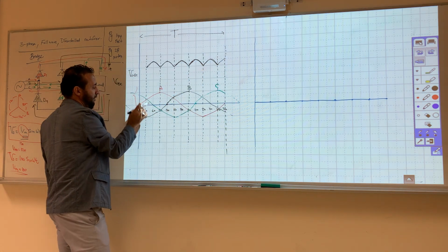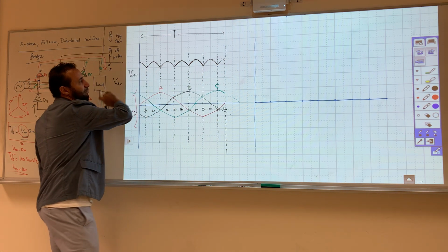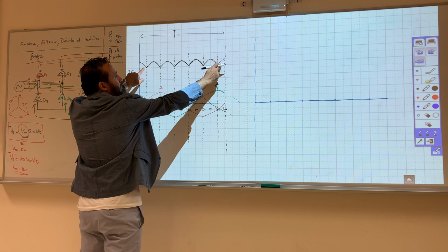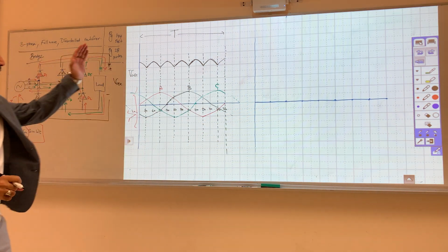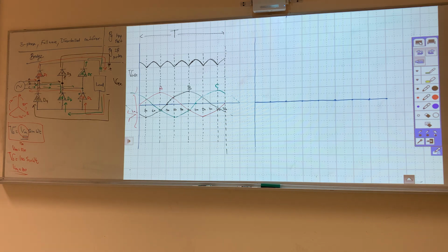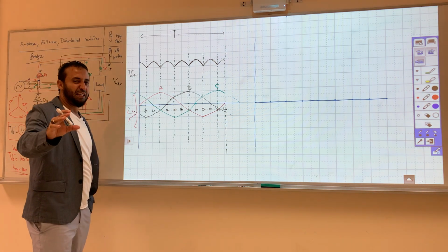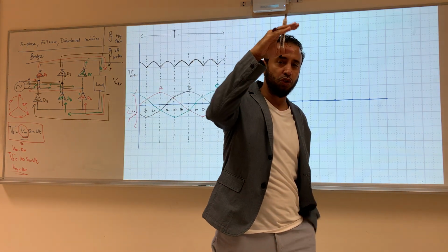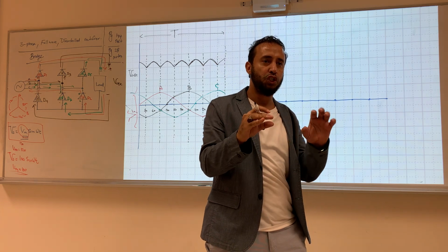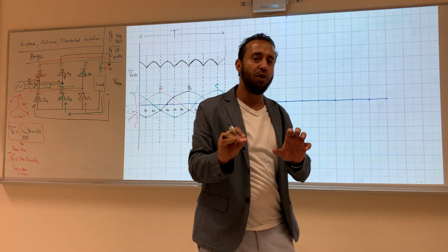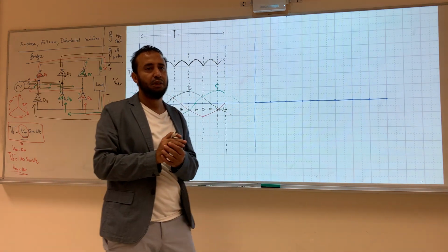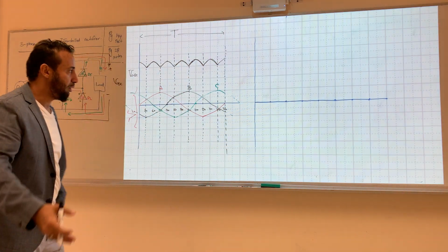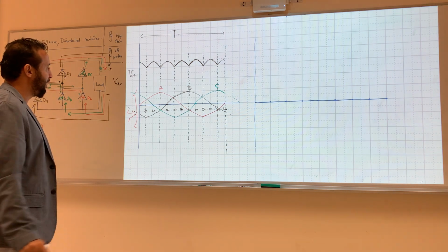And this part will make this. So I have 1 pulse, 2, 3, 4, 5, 6. 6 pulses per side. And that's my peak. You will see that even in lab. I think I already explained it for some of you in lab: the peak, you're not going to see it in the oscilloscope. So you need to assume that instead of 0 being your x-axis, -1 is your x-axis, and you will assume that -1 is 0. You will see that the peak is around 4 boxes, 4.5, 5, something like that.